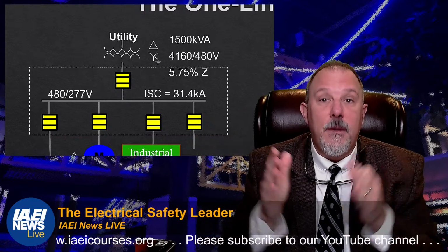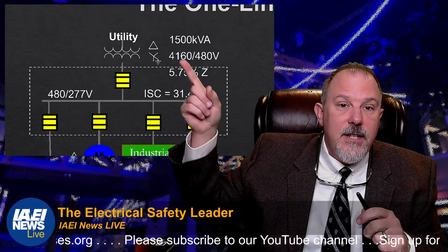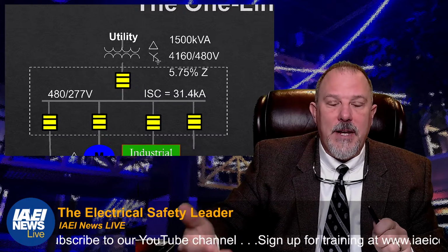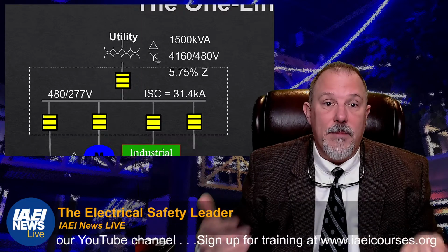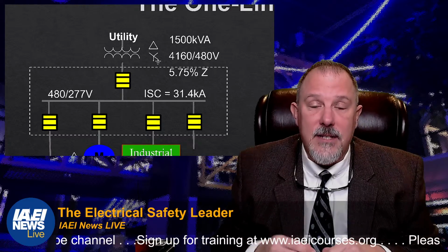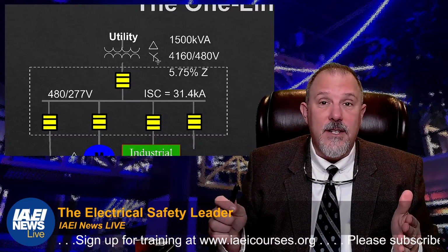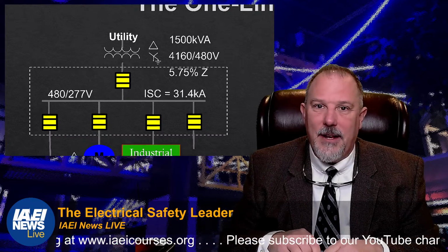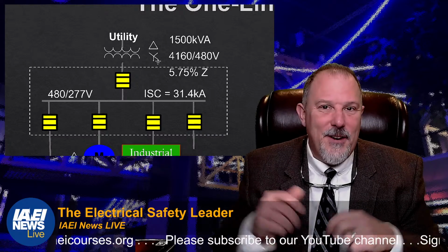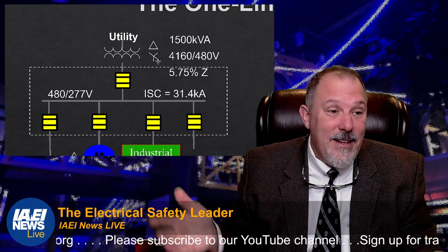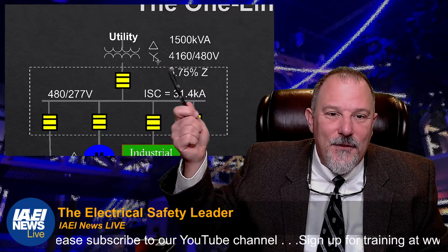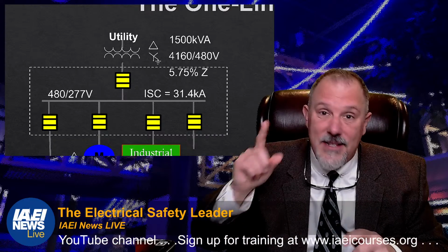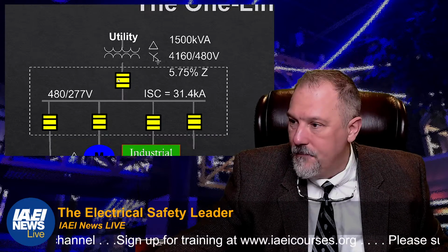And just think if you messed it up. Just think if you did a copy paste of that delta and put it here, and now you're out getting specs back on a delta system, an ungrounded system. You might get somebody come back and say, hey, you got an ungrounded system, I'm going to quote you that way because the code requires an alarm system and the monitoring for ground faults. Why did they quote that? Because you screwed up the drawing. Drawings are very critical and very important. They'll be stamped by a PE when they're done, hopefully.